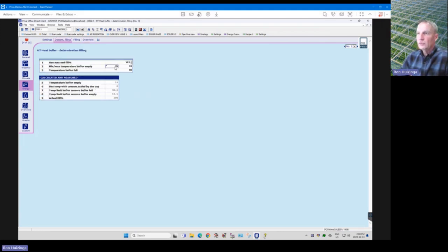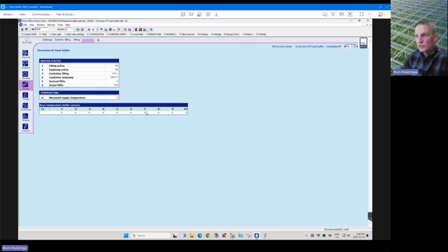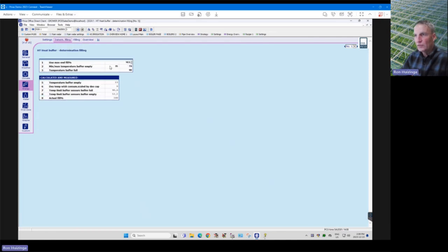So with these measurements here, if somebody's played around with these points, that overrides the return sensors that are reading here in the back, coming in the bottom of the tank. So if by mistake you put this to 70 and 70, then it thinks it needs 70 degrees in the bottom of the tank, and when all the sensors are 70, it's cold.